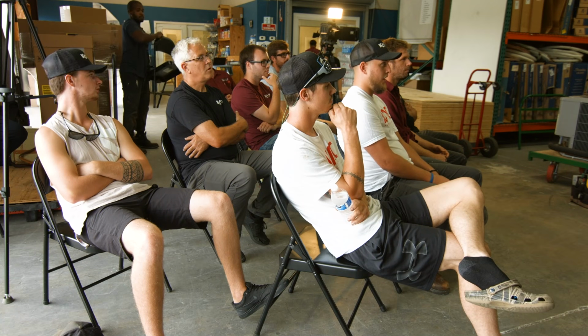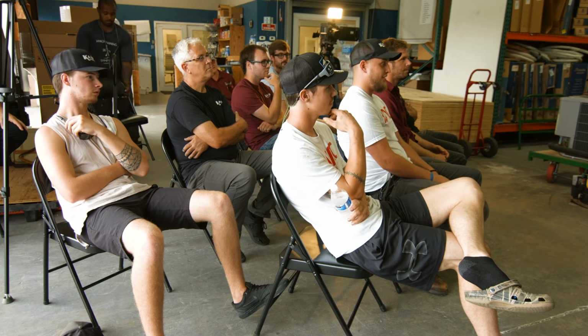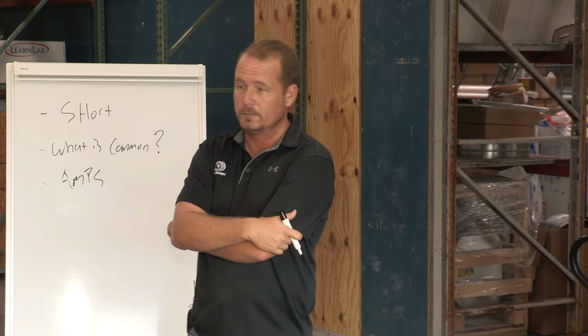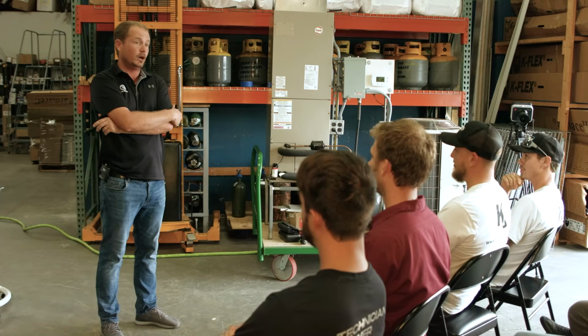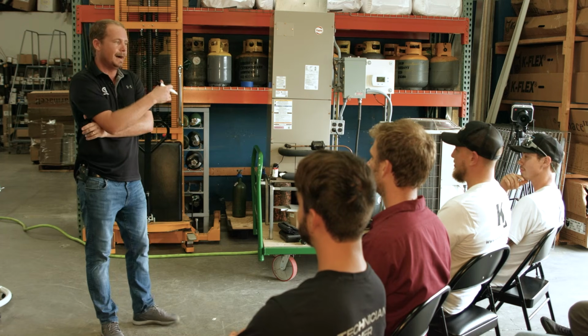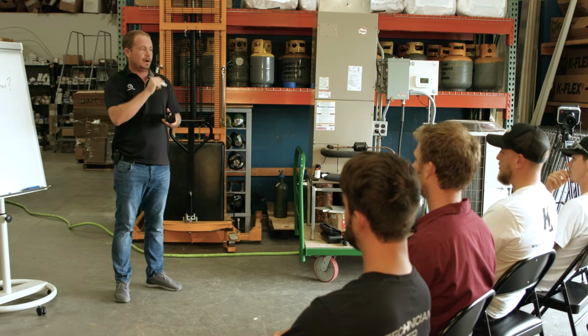Sam? At some point, some high current went through that fuse. Too much current through the fuse, right? That's what you know. There's too much current. And what is the most likely cause of too much current? A short. A short, right? And a short that bypassed a load. So it went straight from one side of the power supply to another.